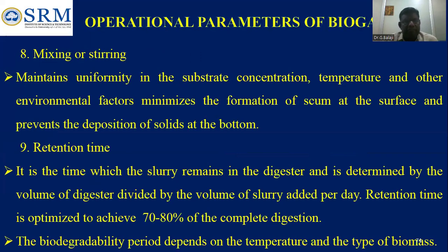Mixing or stirring. The dung and water mixing should be proper, to maintain uniformity in the substrate concentration, temperature and other environmental factors, minimize the formation of scum at the surface, and prevent the deposition of solids at the bottom.